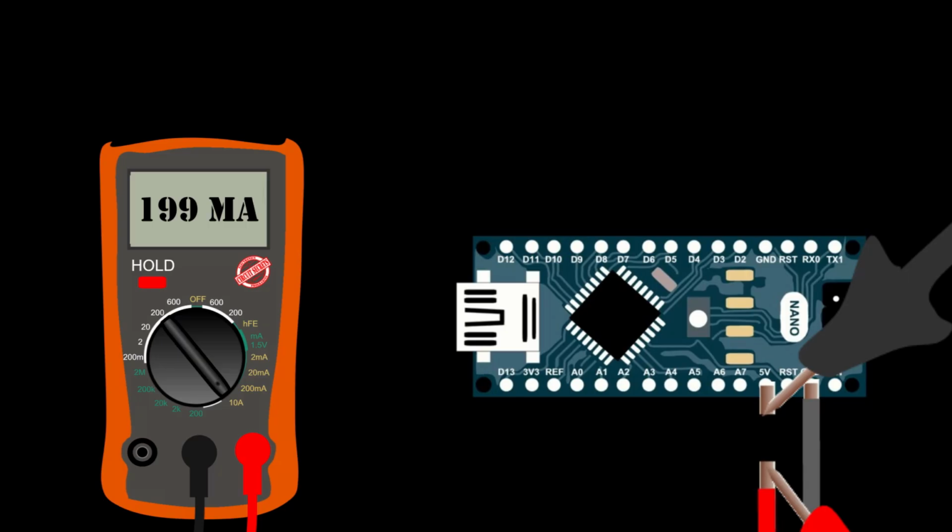When measuring current, the meter must be placed in series with the circuit. This is the way a multimeter is connected to measure current. The positive terminal is towards the positive source, and the negative is towards the negative source. When measuring current with a multimeter, set the meter to amperage or amps before connecting the circuit.